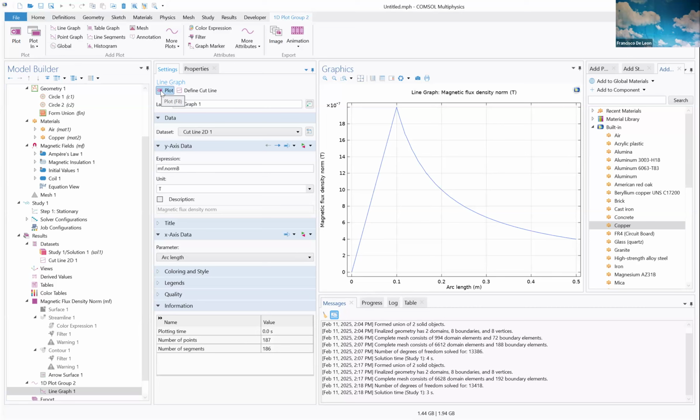At the center of the conductor it starts at 0 and rises linearly up to the maximum point at the radius, and then it decays exponentially. It's not exponentially, it would be a log decay, outside the conductor. So this is the typical figure that we will see. Some magnetic field inside, nothing in the center, maximum at the surface, and then it decays outside in the air.